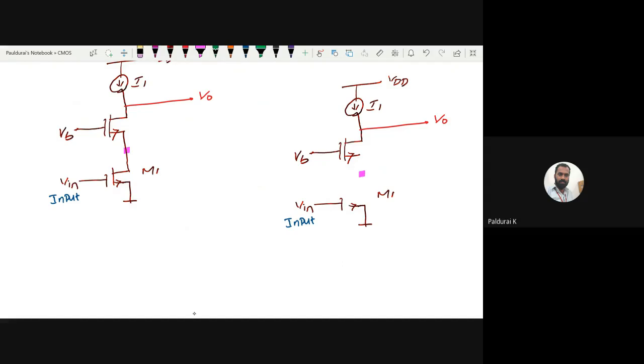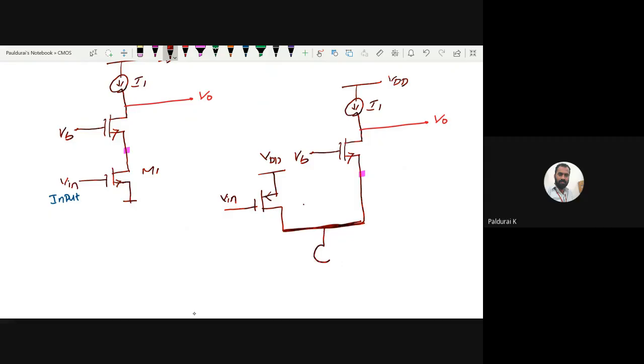So just take this input transistor. NMOS becomes PMOS. So first draw the PMOS. PMOS, this is my VDD, right? It must be properly biased. So this is my VIN actually. Now connect this. So when you are connecting these two, you are getting a junction. So it must be properly biased, so you want to add one additional current source. That's it. This is my M1. This is my M2. So any doubt in NMOS cascode and its folded version?